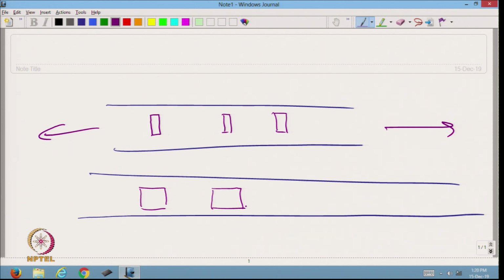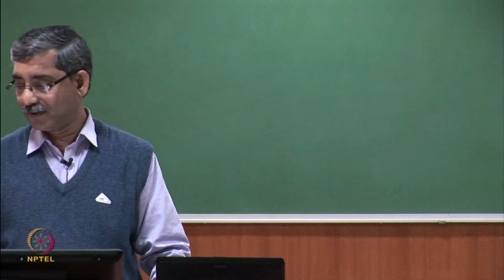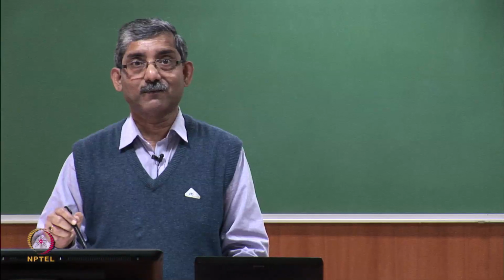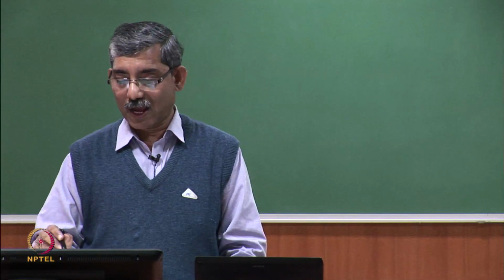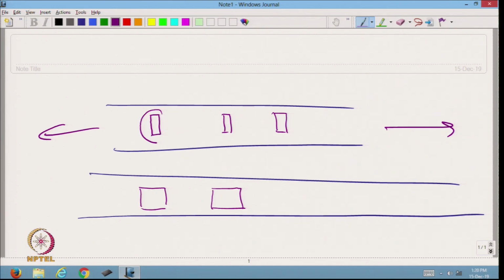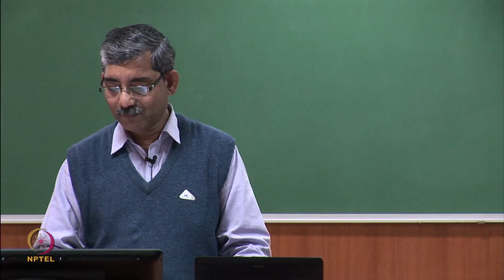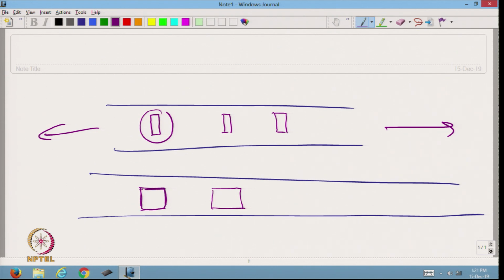This will indirectly show the level of stretch, and if we know the stress strain characteristics, we can predict the amount of stress. So, the manufacturers themselves put this rectangular shape, and the required level of pressure will be achieved when it becomes a square.